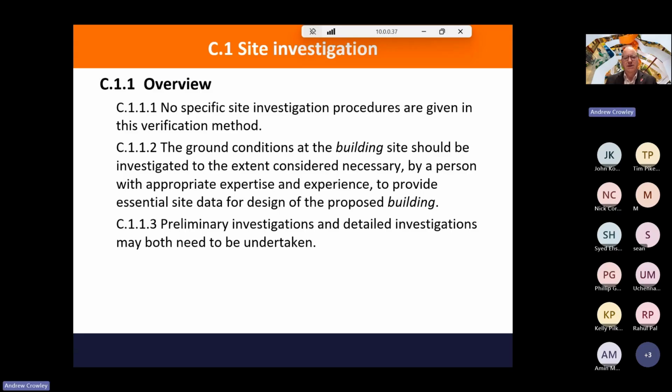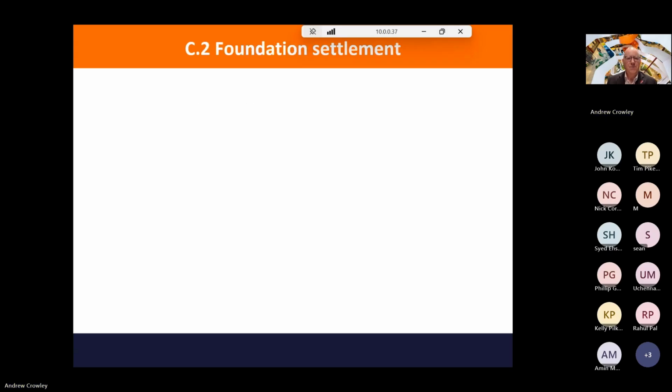And your friendly geotechnical engineer should produce a friendly geotechnical report which contains all those soil parameters that you need to design your foundations. It needs to tell you what your effective angle of shearing resistance is, or your cohesion and so on, as well as your unit weights in your soil, the type of soil you're dealing with, and any presence of groundwater.